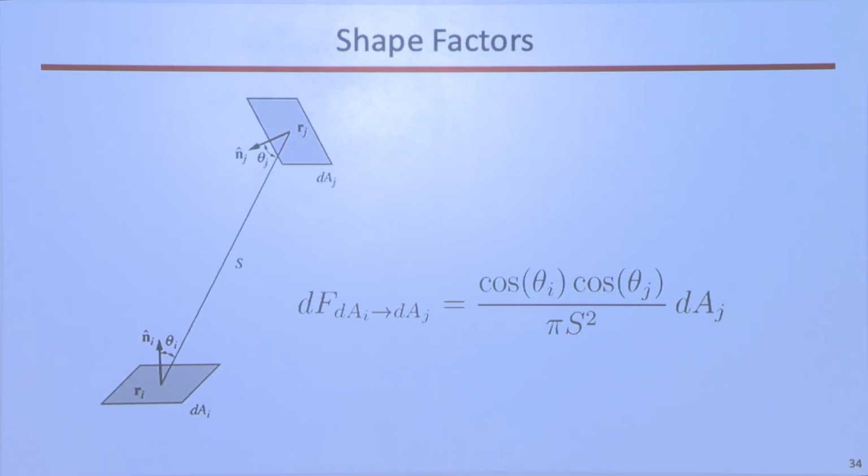Okay, so in order to map this, we get a picture of the ember pile, get all the temperatures and emissivities, and then apply these shape factors. I think all of us have had this in elementary heat transfer, a shape factor analysis, and that's given by this equation here. The intensity of radiation that goes from the bottom rectangle to the upper rectangle is given by this equation.